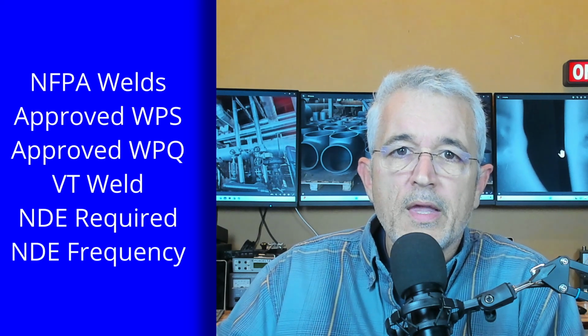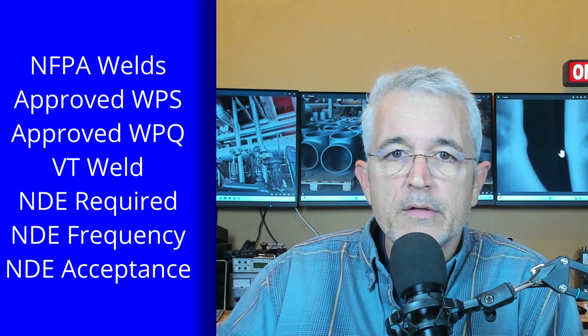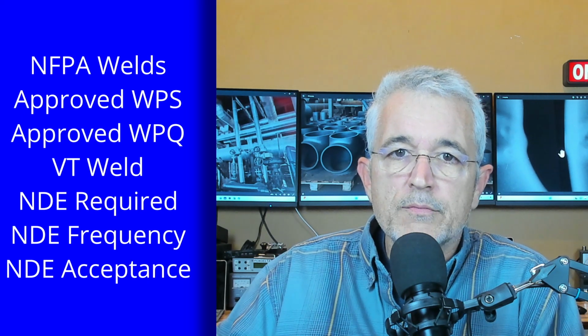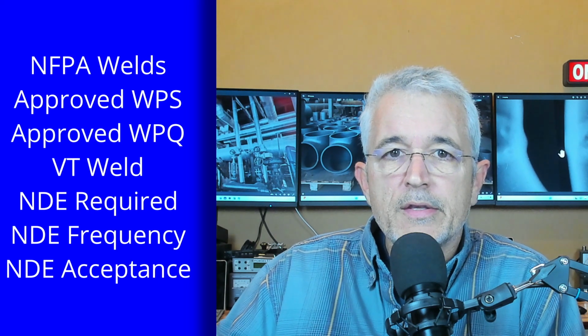And then, what is the NFPA non-destructive testing requirement, such as for X-ray? And the percentage based upon the design code. How often are the welds X-rayed? And the NDE acceptance criteria. So if a weld is X-rayed, how big can each indication be? How much lack of fusion? How much lack of penetration? So this is the big question.